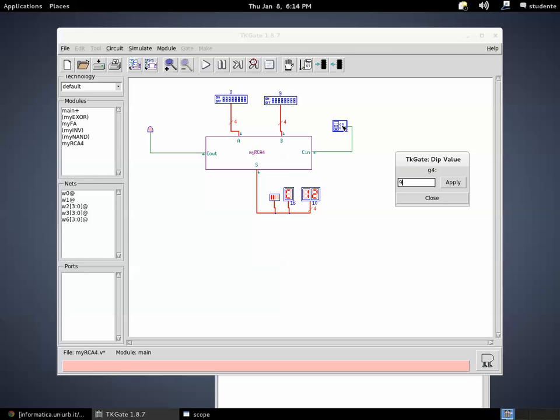Now let's look at what happens if instead of having 0 as a carry in, we switch it to 1. So the effect is adding 1 to the result. In fact, the carry in is like a 1 added in the least significant position. So this means that it corresponds to a third operand taking value 0001. So it is exactly as if we added a third number taking value 1. So we can use the carry in to add an extra 1 to our result.